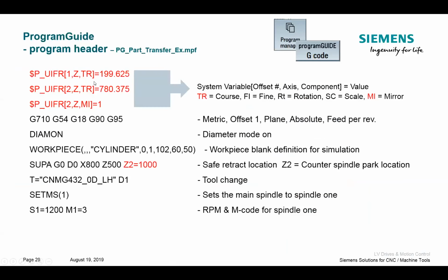So what I like to do, since I have known values, and I'm working this from a real machine, we'll say, is write them right from the part program. This is a quick, simple way for me to write to the coordinate system and write directly to the first work coordinate. That's why there's a number 1 here. That would be G54, which component I'm writing to. Remember, we're writing to the z-axis, and where within the z-axis.